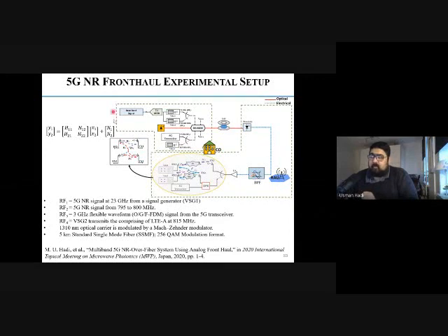So we are now relying on the wireless part, where you have already reached the electrical amplifier here, and you have the diplexer to switch between TX1, the transmitter, and TX2. And then it behaves like a MIMO system, which is multi-input and multi-output. So you have TX1, TX2, RX1, and RX2. Here I'm just using two receivers and two transmitters. So TX1 will interact with RX1 and RX2 simultaneously, and TX2 will also interact with RX1 and RX2 simultaneously.